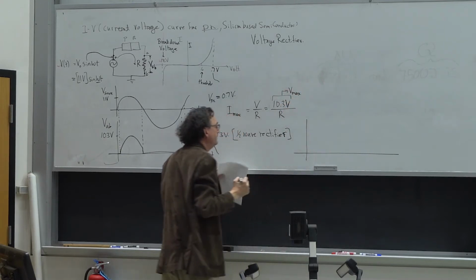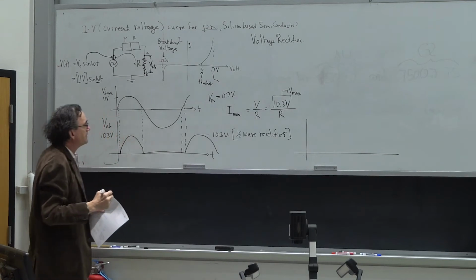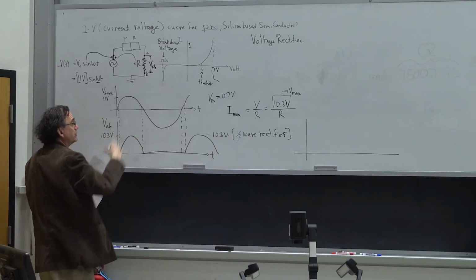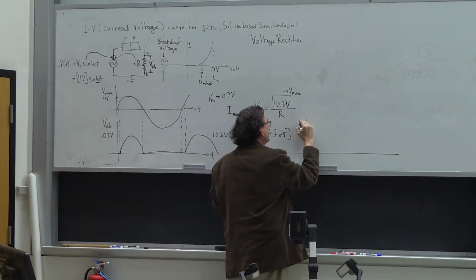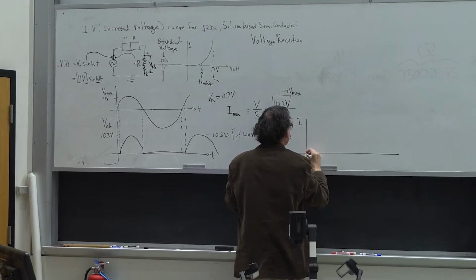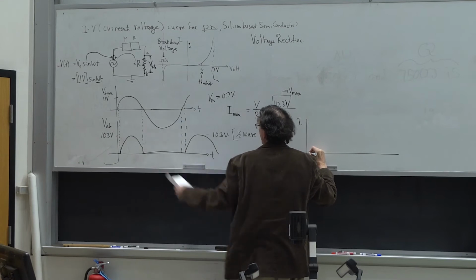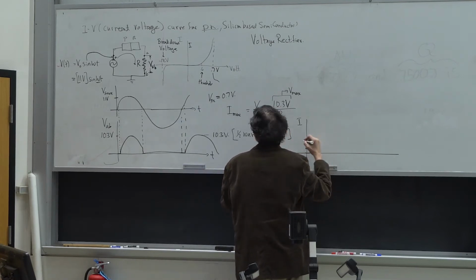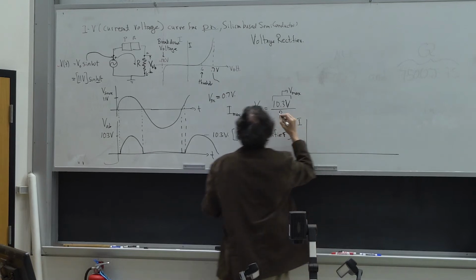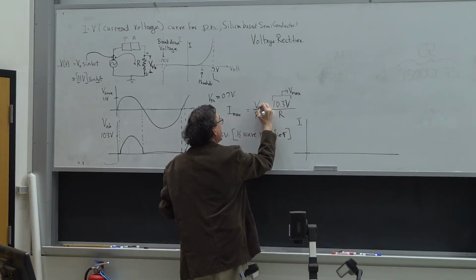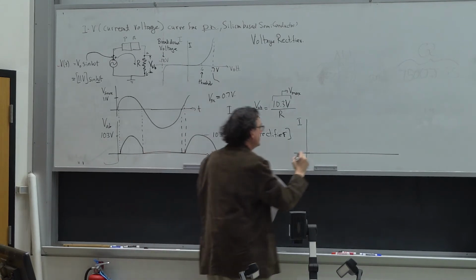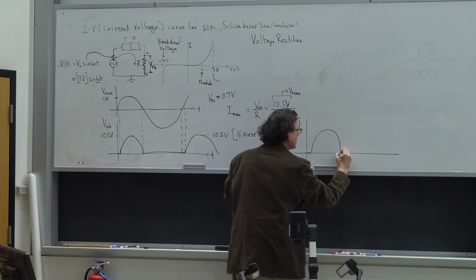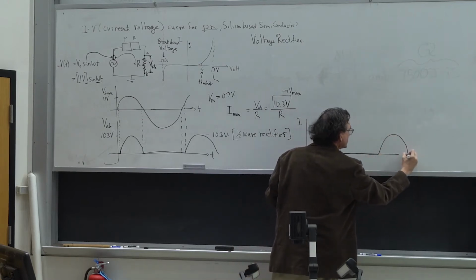resistor. Right? And so therefore they're proportional, right? This curve in voltage is going to be proportional to the current flowing through the resistor. So it will look exactly like the voltage plot, VAB, only I just divide it by R. I forgot to put that, VAB divided by R. And so it's going to have the same form. Right? It's going to go like this, and like this, etc.